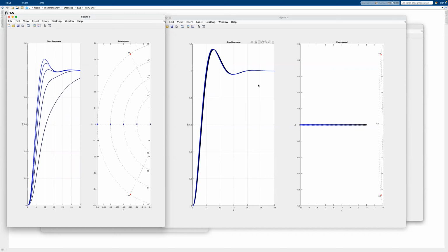So if it's 0.25, it would take 16 seconds to settle down. And that's exactly what the system behavior looks like. So this whole thing here is sufficiently fast so that in the first couple of seconds, we get rid of the effects of the third pole, and the overall system almost always behaves like the second order portion of it. Whereas here, that's not the case.